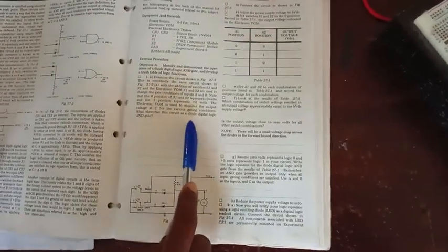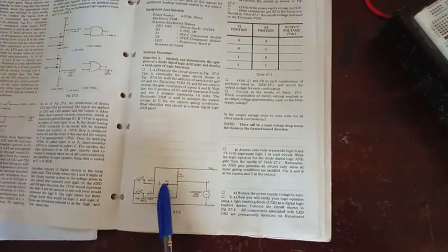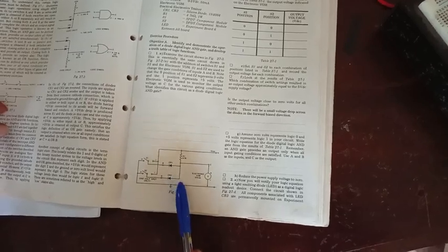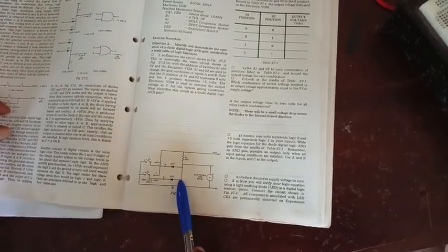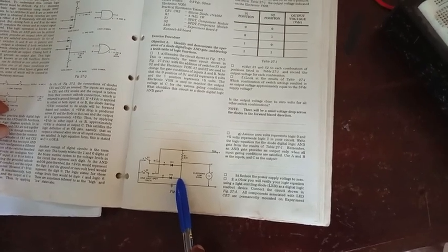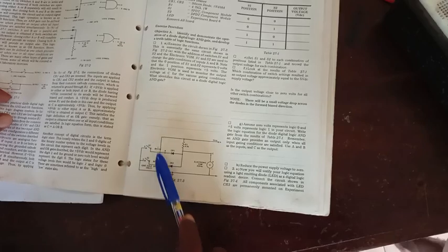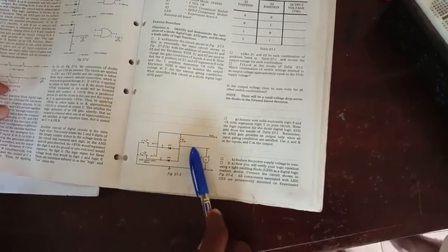We identify this circuit as a diode digital logic gate because we have 2 diodes, and the anode sides of those diodes are connected to the positive power. Therefore the cathode side will be grounded. This shows that we are going to have an output only if both switches are on.